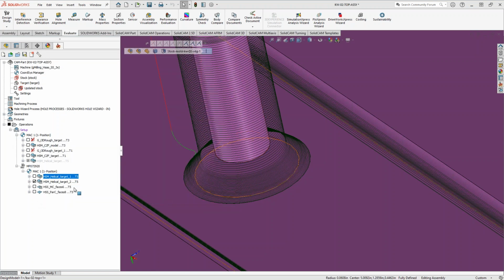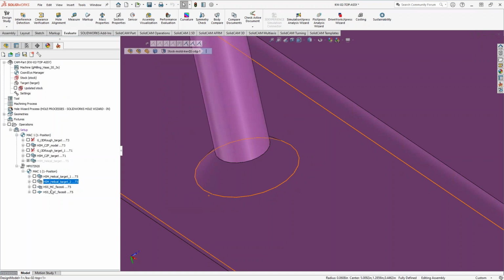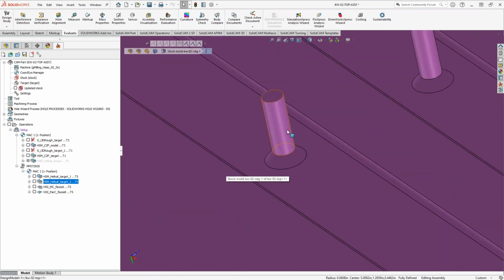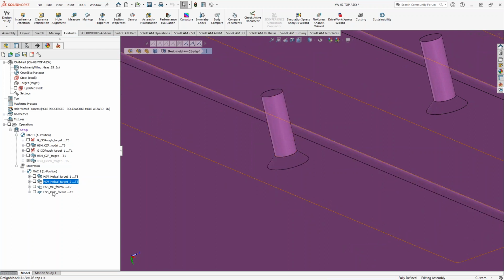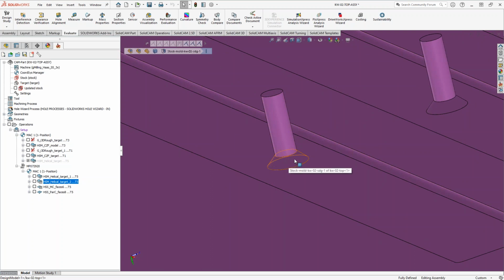Yep. And with the idea of breaking it up, then you can actually think in terms of not just HSS, but if this is purely vertical, this opens itself up to profile. Yep. I probably would do all the verticals with profile, and then with profile, definitely you can give it that 30 thou step over. And then in the HSS, when we do this 3D portion, I can give it that 3 thou step over.